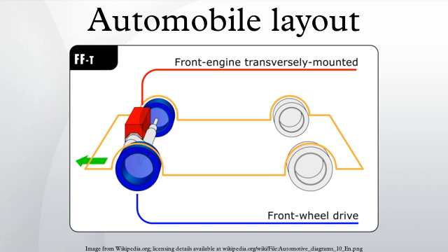Torque steer can be addressed by using a longitudinal layout, equal-length drive shafts, half shafts, a multilink suspension or center-point steering geometry. In a vehicle, the weight shifts back during acceleration, giving more traction to the rear wheels. This is one of the main reasons nearly all racing cars are rear-wheel drive. However, since front-wheel drive cars have the weight of the engine over the driving wheels, the problem only applies in extreme conditions such as attempting to accelerate up a wet hill or attempting to beat another RWD car off the line. In some towing situations, front-wheel drive cars can be at a traction disadvantage since there will be less weight on the driving wheels.